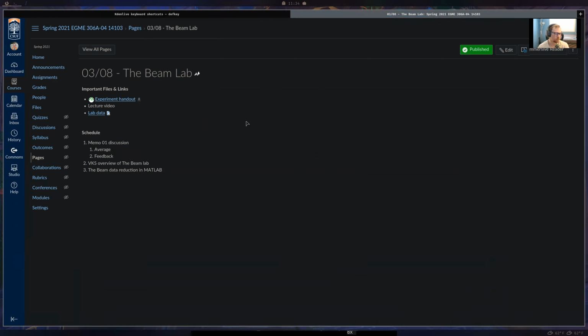When I was trying to calculate the strain of the material, I would compare it to the strain that the resistance gauge collected, and it was a little bit off. Was the gauge length different, or is this resistance gauge kind of a little off from what we might calculate anyway? Yeah, the gauge length is going to be the same. If you have the strain gauge, that's getting the strain directly, so you don't need to worry about the gauge length or anything like that.